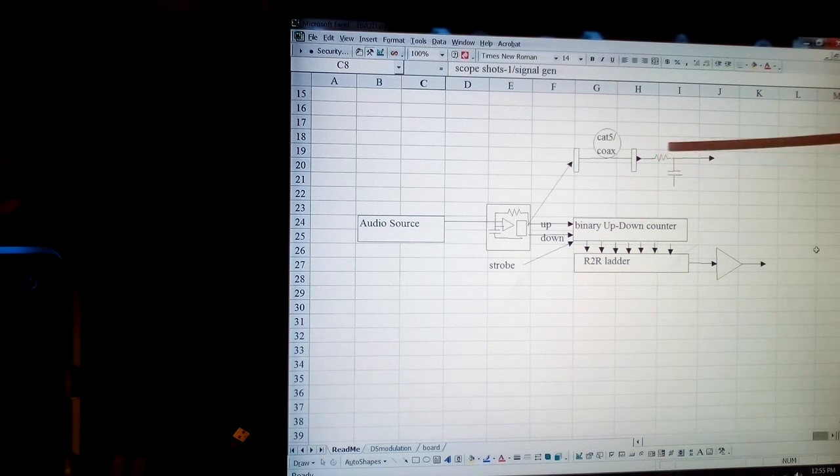The little resistor capacitor reconstruction network is really all it takes to convert the delta sigma modulation back into audio. This is not very complicated for the recovery circuit. However, the pulse train's coming at 4 to 10 megahertz, so if you're going to run it any length of distance, you're going to probably need something like Cat5 or coax. I don't think regular old audio twisted pair is going to work. But in specialized applications where you need a lot of reconstruction circuits, that's really cheap.